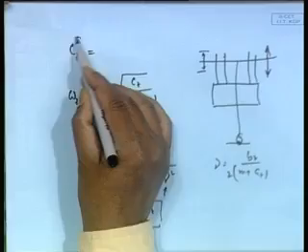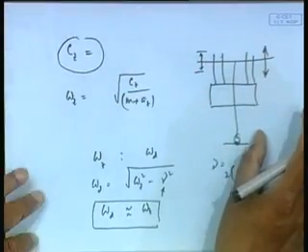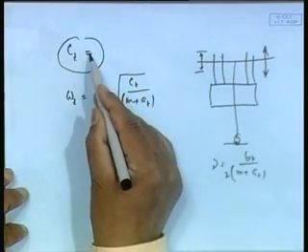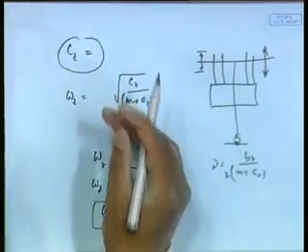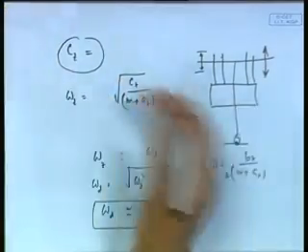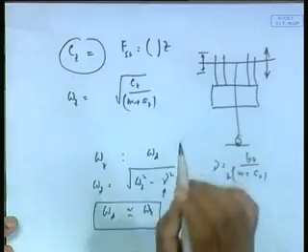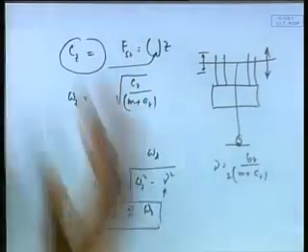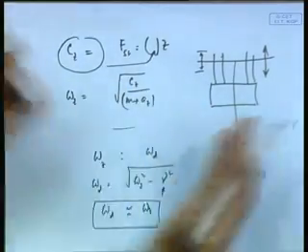Now, for this I need this. What is Cz? I think we will talk about this Cz in tomorrow's class, because we do not have time, but we understand here one thing, that Cz is the hydrostatic restoring force. So, it comes purely from hydrostatics, there is no hydrodynamics. Having said that it is hydrostatic, it is not exactly the buoyancy force, which is what we will try to find out. It is the unbalanced hydrostatic force. And remember that we have always called the hydrostatic force Fs as something into Z, and this something is this Cz. So, we will derive that Cz expression tomorrow, so that we can estimate these values for practical structures and figure out which range they are in.